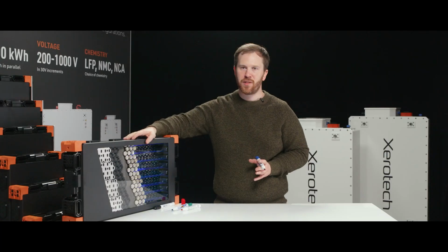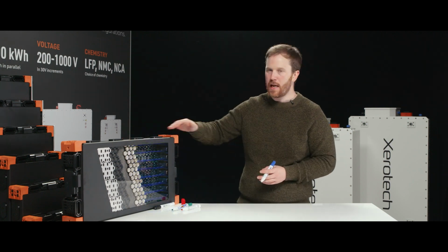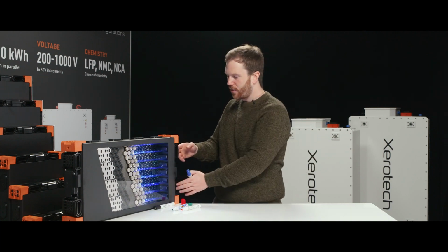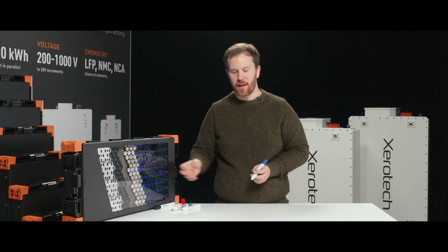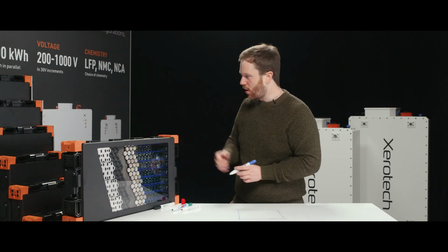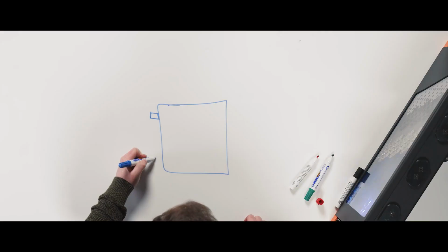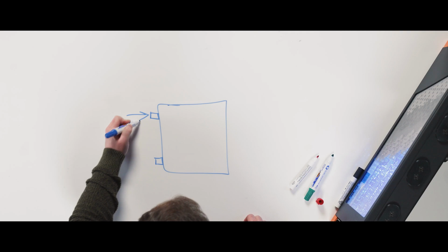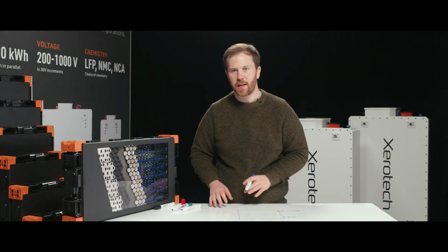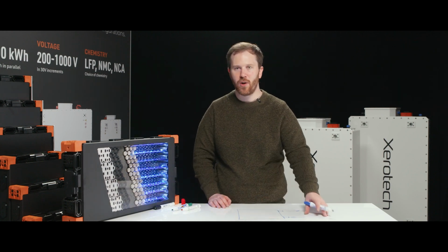What we put in battery systems in the vast majority of commercial batteries on the market today is heat transfer systems. So even in a Xerotech battery, we can't control the temperature of the battery. That's done by an external system. So if you've got a module or a pack back here, that's got a coolant in and coolant out. What we give you inside of our batteries and every other battery supplier out there is a heat exchanger that's going to exchange heat between the battery cells and the cooling liquid.